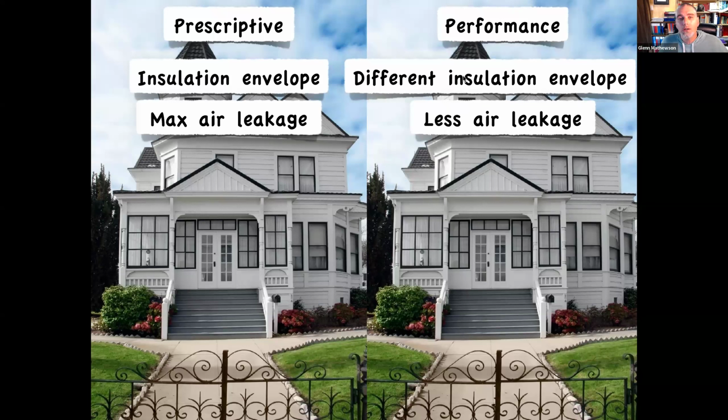Less insulation in your insulated assemblies. This is kind of the truth, be told. This is where we see a big part of why this option is chosen, because air leakage can be tightened up with building practices, whereas more insulation is hard dollars. So you trade off dollars of product for more meticulous installation practices in a nutshell.